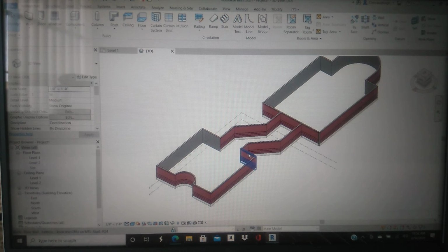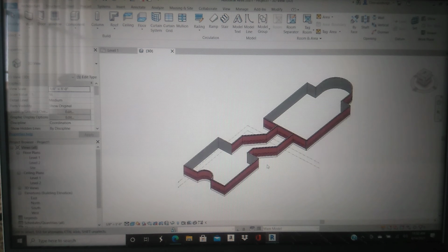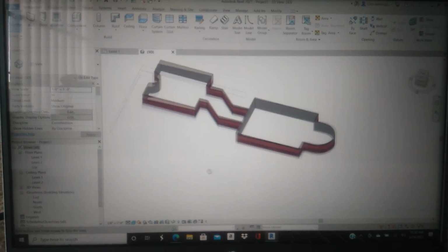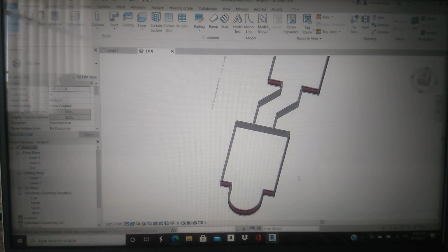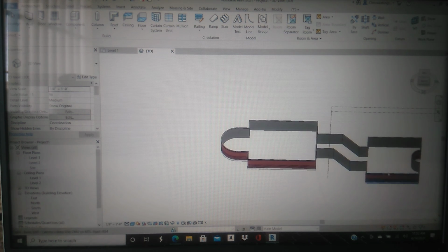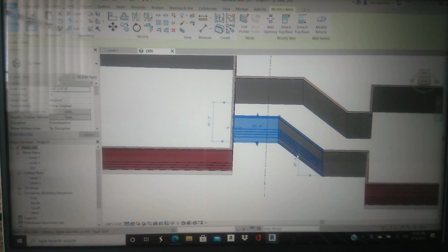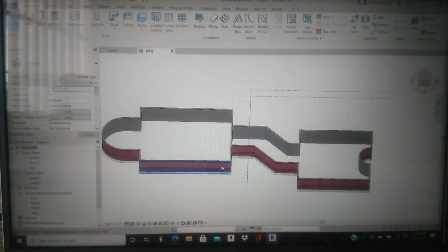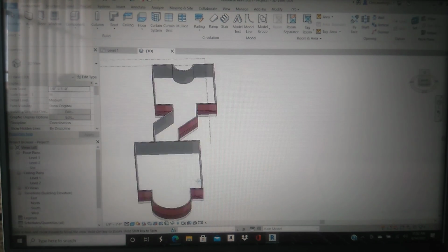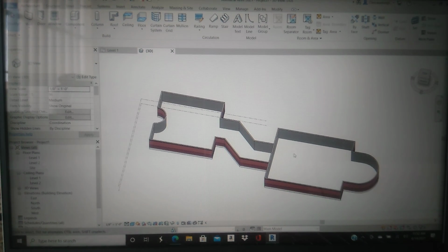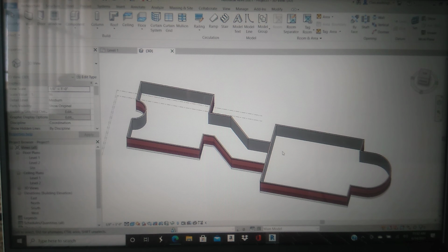Now when you click off of the model, oh, this one didn't go, there it is. Now when you click off of the model, you hold down the shift, press down on the mouse wheel, and you can orbit your model and actually see what your model should look like. So these are some walls we have to clean up. We have to have those facing outward. The space bar, they're facing outward. Okay? So there it is, essentially a portion of your building. I think for the next video, we will go ahead and add some interior walls.